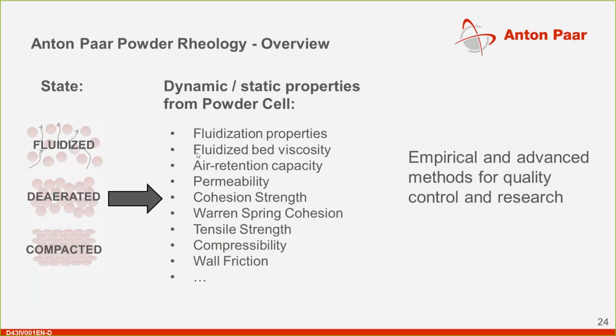It's possible to look at the cohesion strength and the Warren-Spring cohesion. So the cohesion strength is the cohesion in a deaerated state for powders that are fluidizable.